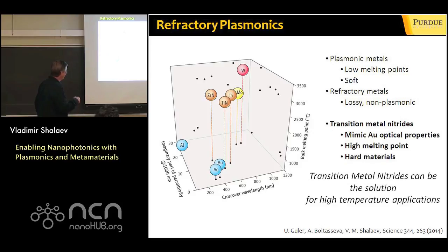So what you could see here are the plasmonic materials commonly used until recently, silver and gold. They indeed become plasmonic. They are shiny. They have this metallic luster. They reflect light. Aluminum too. But the problem is their bulk melting temperature is very low. Therefore, when you nanostructure these materials, even at relatively low intensities of light, the temperature locally increases up to 350, 400 Celsius, and that's enough to damage your nanostructure, which precludes durable use of this device.